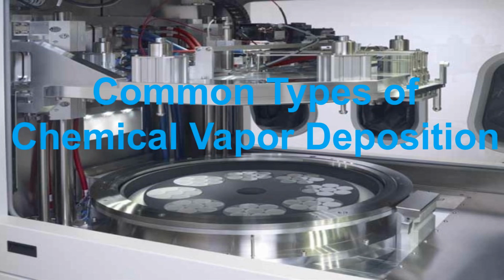Now let's discuss the common CVD techniques which are used in laboratories. One of the most commonly used techniques in a lab is known as atomic layer CVD. This is a very interesting type of CVD. In case you want layer by layer deposition on the surface of a substrate, you can use atomic layer chemical vapor deposition.